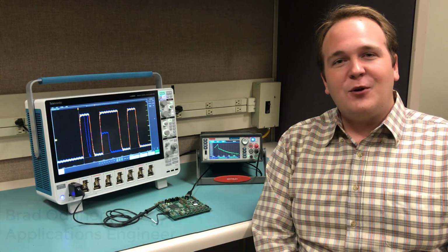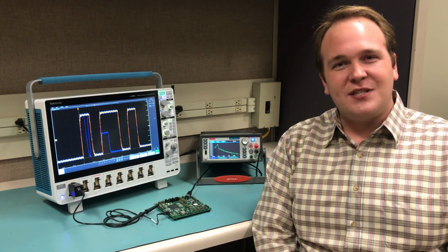In this short video, I'm going to be showing you some interesting applications of a Keithley Source Measure Unit, including simulating electrical brownouts and dropouts. Along the way, I'll be showing you how to configure sweeps and pulse trains with a Keithley 2461 SMU. We'll be viewing the results of these dropouts and brownouts with the Tektronix 5 Series mixed signal oscilloscope. For a device, we're using the 5 Series' demo board.